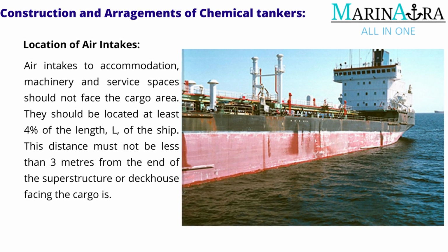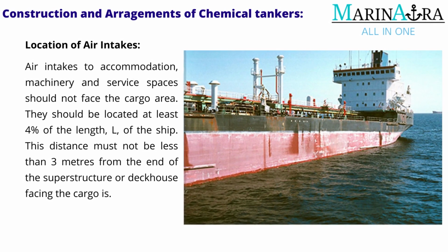Machinery and service spaces should not face the cargo area. They should be located at least 4% of the length, L, of the ship. This distance must not be less than 3 meters from the end of the superstructure or deckhouse facing the cargo area.